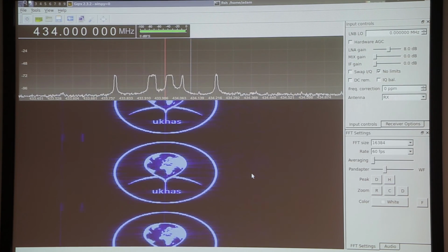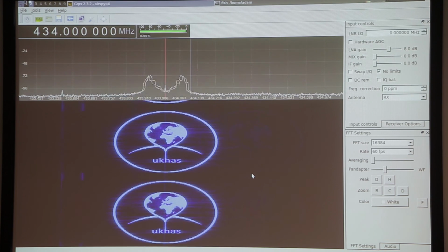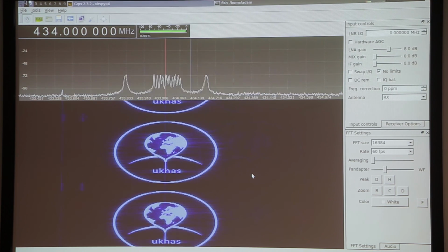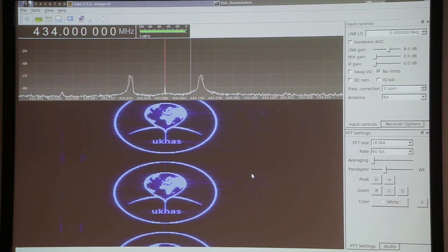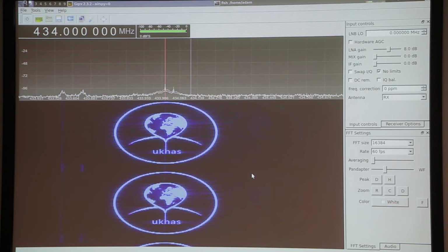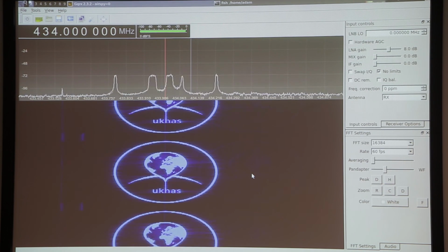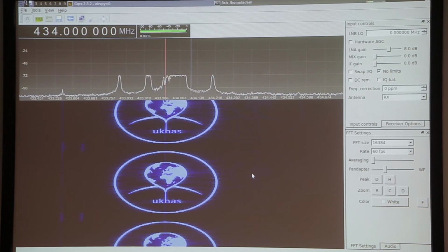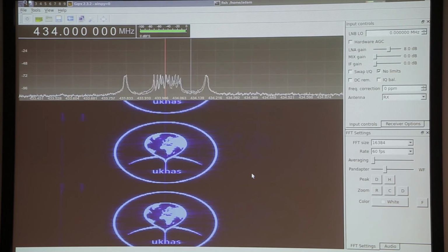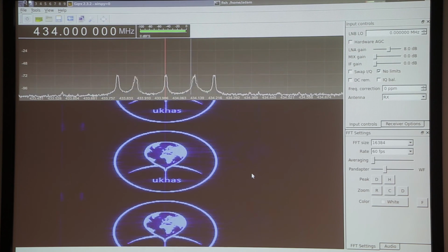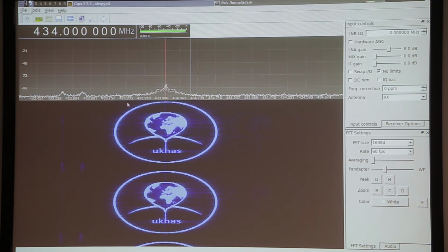At any moment in time, you want to transmit one line of this image, and you break that line into pixels, and each pixel is one frequency. So all you need to do is see which pixels are on for each line, and then generate a signal at that frequency, and you add them all together, and you transmit that. And then when it receives, it shows you what frequencies were present. So whenever you are putting a frequency in, you get it out on this. And yeah, ta-da. So this does actually mean the BladeRF is working again.